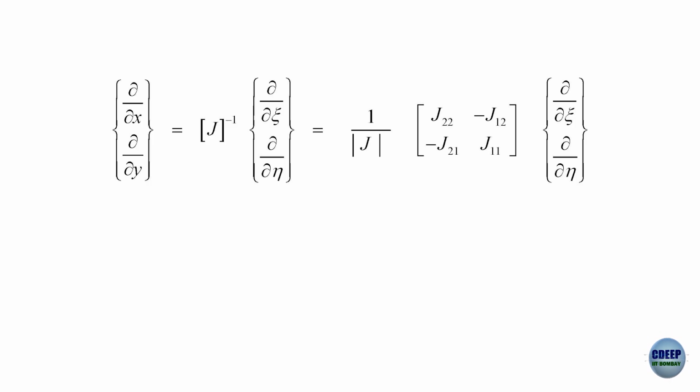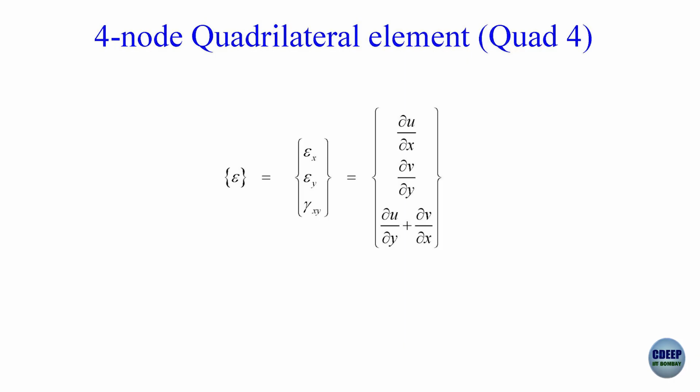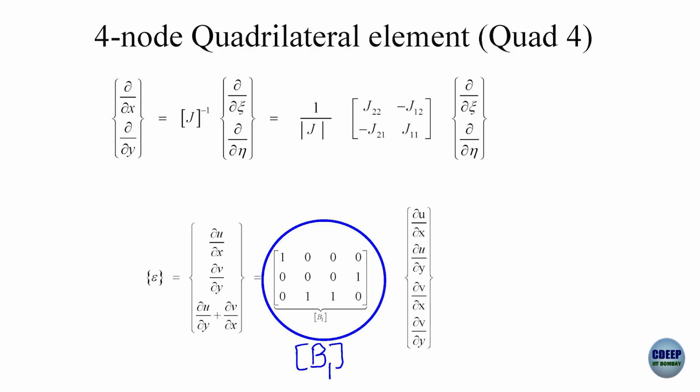So, we did the strain to displacement relation now: epsilon x, epsilon y, gamma xy, let us say. That means dou u by dou x, dou v by dou y, and a combination of cross derivatives we will need. So, we will need to transform that, which we attempted to do in terms of the nodal displacements, ultimately that B matrix. So, what I am going to do, you please see, this is a structure you can use for any element for that matter from now.